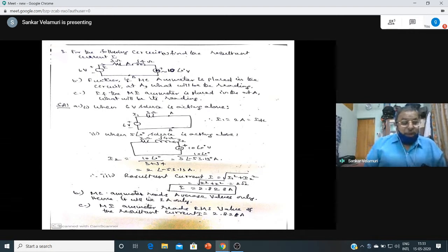Okay. I got this idea because once the students put a moving coil ammeter, I observed that in the AC source it was not reading. What is this? Why is the ammeter not reading and the machine is functioning? All those things came up, because by mistake the student batch had put a moving coil ammeter. So the moving coil ammeter reads only the average value. Here the average value happens to be equal to the DC component, 2 amps, so it should read only 2 amperes. If there is no DC component here, and you put a moving coil ammeter instead of a moving iron ammeter, the meter will not read 0. You may say that the meter is not functioning and other things.